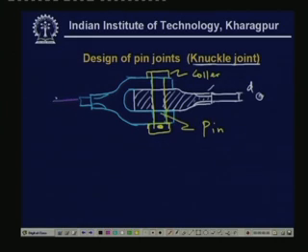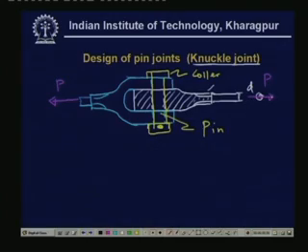Normally we apply two forces, so this joint takes a large tensile stress. What happens when we apply a tension here? This pin arrests the motion of this part 1, let us call this part 1 and this part 2. So it arrests part 1, and this part arrests the motion of part 2. So this is the purpose of this pin.